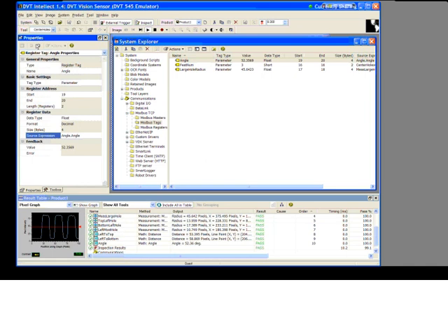Back to the OPC configurator. Remember that we mapped these values to registers 16, 17, and 19 respectively. And that number of features is actually a short, which is a 2-byte integer. And the other two values are of type float, which is a 4-byte floating point number. All right.